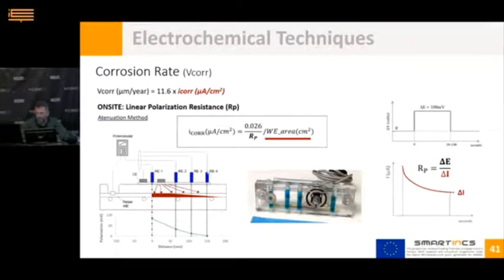The objective is to detect the critical length from which the reinforcement is no longer affected by the test, and thus to know the area that is being evaluated. With this data, the polarization resistance and the corrosion density are obtained.